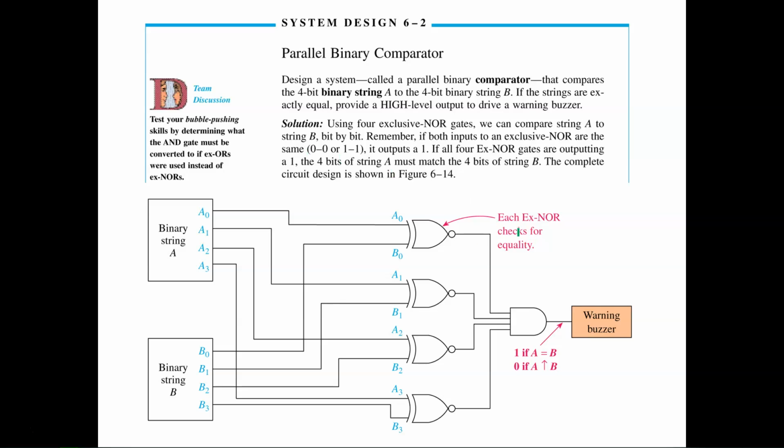So we're looking at another setup here. These are exclusive NOR gates. What are we looking for with exclusive NOR gates? You're looking for signals that are supposed to be the exact same. You're looking for either 2 highs, or 2 ones rather, or you're looking for 2 zeros or 2 lows.